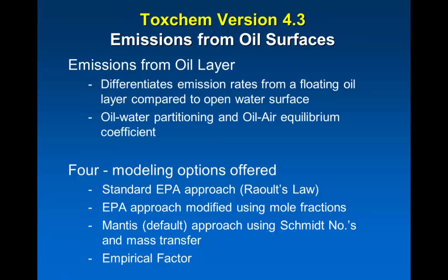The methods are not really very well defined for modeling the emissions from the oil layer, and that's why we chose to provide you with 4 different methods in Toxchem. The first method which we have implemented is a standard EPA approach. This comes from the Water 9 document, in which a procedure is specified to model the emissions from the oil layer, and it's based on Raoult's law.